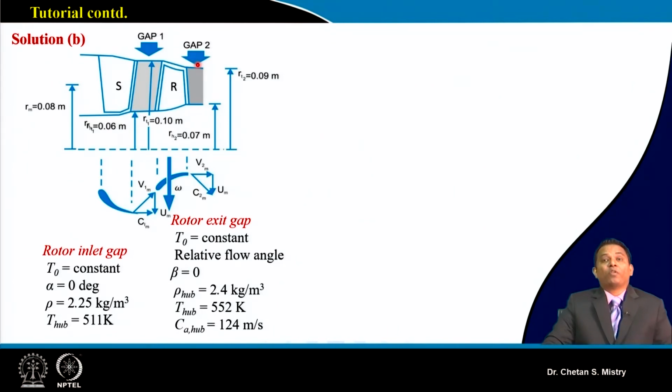We are looking for our static pressure, because static pressure and total pressure are interrelated. Now the question is how they are interrelated. They are interrelated through my critical Mach number, or critical velocity ratio.